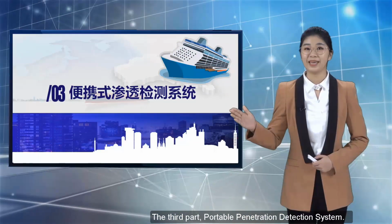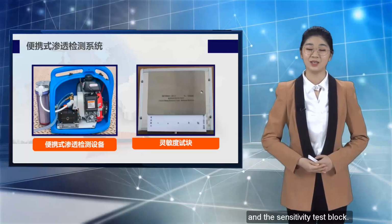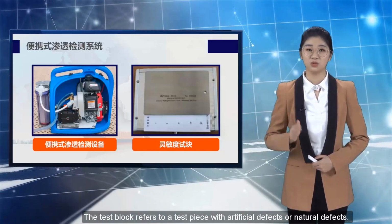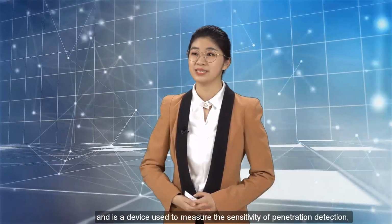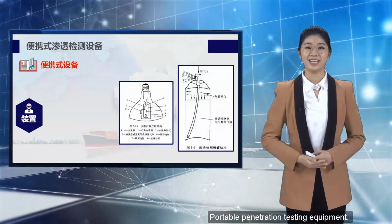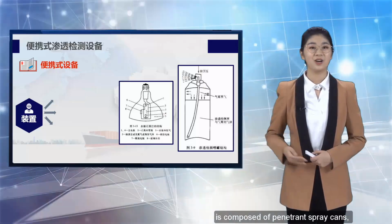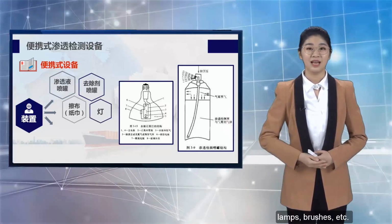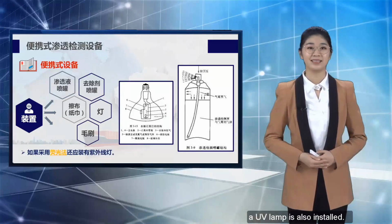The third part, portable penetration detection system. In the picture are the portable penetration testing equipment and the sensitivity test block. The test block refers to a test piece with artificial defects or natural defects, and is a device used to measure the sensitivity of penetration detection, so it is also called a sensitivity test block. Portable penetration testing equipment, also known as a portable pressure spray device, is composed of penetrant spray cans, remover spray cans, developer spray cans, wipes, lamps, brushes, etc. If the fluorescent method is used, a UV lamp is also included.